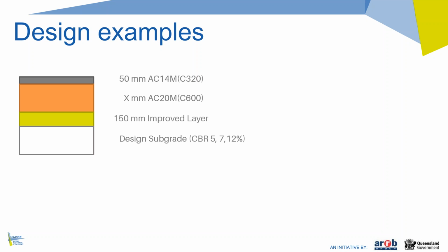But one thing I think has been the message across the different methods is that when we talk about having a pavement that we expect to have a very long life, we just can't ignore the fact that it needs to have good foundation support. For this reason, in the technical note, we're putting in the criteria to require some sort of improved layer plus any additional fill material, so that we can ensure that the top of the improved layer has at least 150 MPa. That's quite a specific requirement we put down in there.